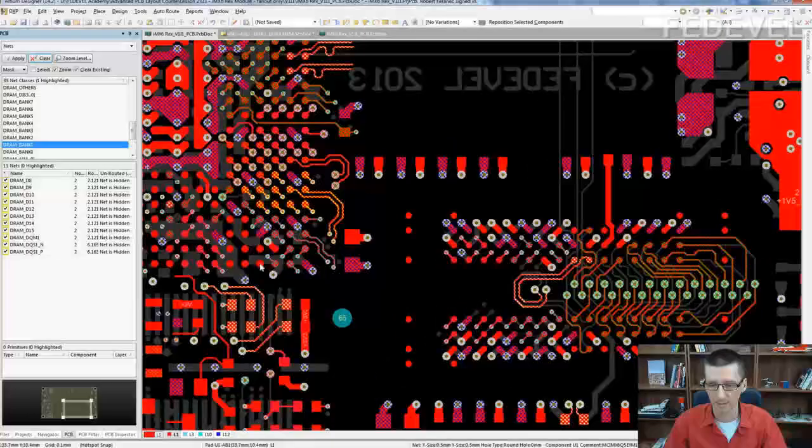The thing is, 2 of our memory groups use the micro vias. So ideally we would like to connect these 2 groups to the top memory chip, because we can do the layout on layer 3. Yes. And there are 2 memory groups which use through-hole vias, and ideally we would like to connect these memory groups to the bottom memory chip. Let's have a look.